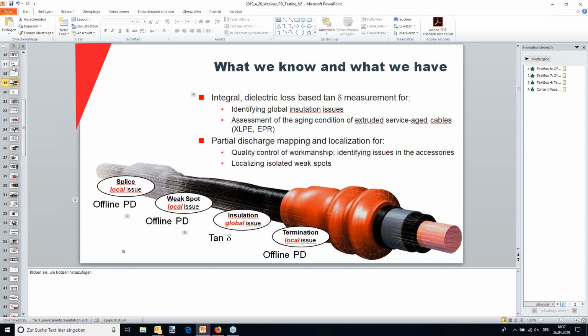If you get anything substantial, from our experience, any defect that is really there, like tracking, damaging splices, or a termination internally, will show in the hundreds of picocoulombs or more, even in the thousands. And if you get a measurement that goes into the nanocoulomb and higher, then that is very different from just measuring 100 picocoulomb in the splice. So both are important.